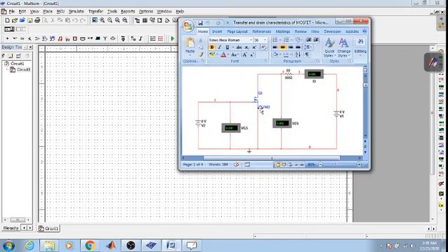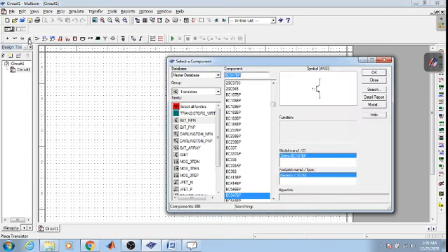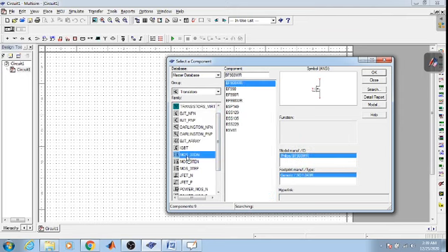So what we require is one MOSFET. So it's a transistor. So go on to a transistor. So this is place transistor. Click on this here in a transistor. So we need to check for MOSFET. So here, MOSFET. So this is the MOSFET. So this is a 3-terminal MOSFET. So you are not having IRF over here.